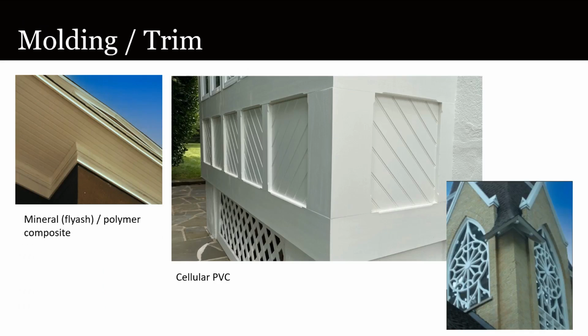Wood trim is typically a painted feature with a smooth painted surface, making many substitute materials with a smooth, paintable, or pre-finished surface appropriate to consider. None of the several possibilities behave exactly like wood, though, and understanding those differences is critical to using them successfully. In fact, the failure to use real wood correctly is responsible for its failure in many applications, as an image David showed earlier illustrated.